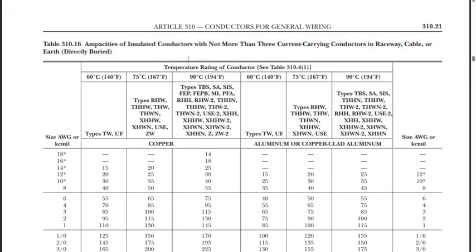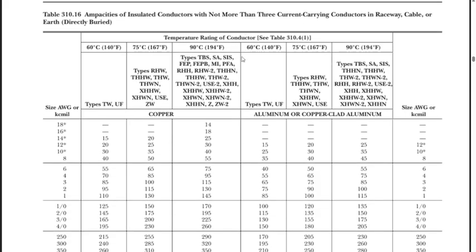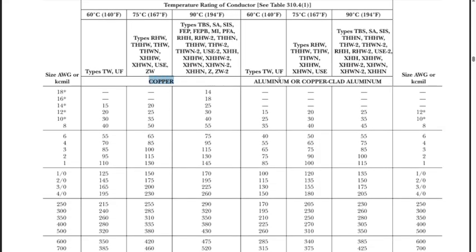Ampacities. Remember what ampacities was? The amperage rating of insulated conductors. Now, we'll unpack this a little bit more because they are telling us there is a caveat to this. There is a qualifying factor to these ampacities, which is no more than 3 current carrying wires in a raceway. So if you have 4, 5, 6, 7, 8 wires, things do change, but we'll explore that a little bit more. But to the point that I want to show you, first of all, copper, aluminum, 2 sides, different sides.